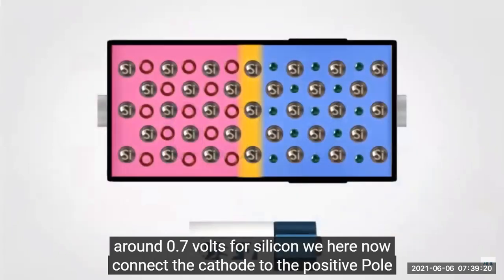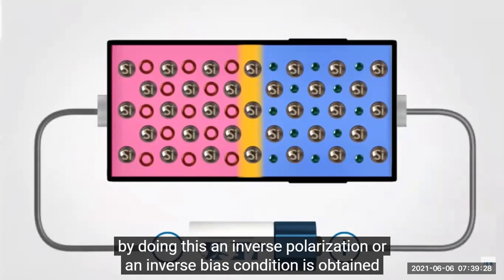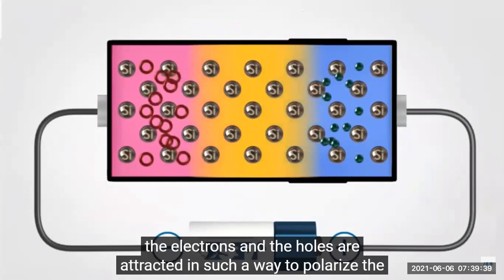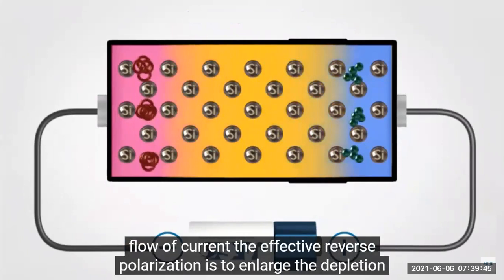We here now connect the cathode to the positive pole and the anode to the negative pole of a current generator, in this case a battery. By doing this, an inverse polarization or an inverse bias condition is obtained. The electrons and the holes are attracted in such a way as to polarize the PN junction to increase the depletion region and consequentially prevent the flow of current.